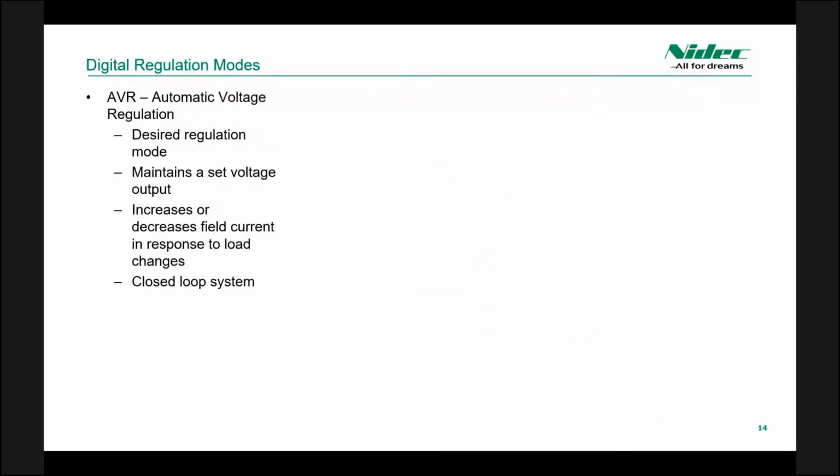All right, so let's continue on to digital voltage regulator modes. There's a lot to choose from, but I'm going to hit the main three that are typically used and talked about. First off, automatic voltage regulation is more or less the desired regulation mode because it utilizes a closed feedback loop, which is ideal when reacting to load changes.